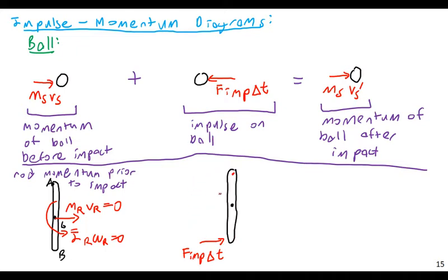In the sense that, if you look here, I don't care which way these go. You can set up your equations with these going either direction. This one we can probably just look at and figure out which way it's going to go, but if you had a more complicated system, it may not be so intuitive, or you may not be able to figure it out using such intuitive methods. And so instead, you might just have to guess one way or another. But it doesn't matter, as long as I'm assuming compatible forces and compatible impulses. If I get a negative number, no big deal. I just know that in reality they're going the opposite direction.